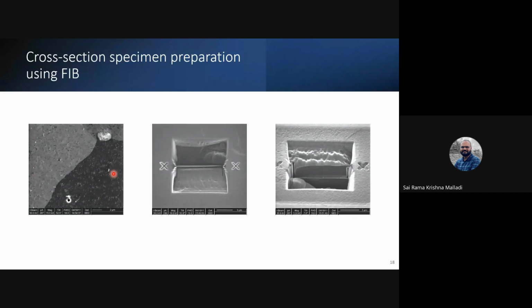So what I can do is, the way you do lithography in clean room processing techniques, I can put in some kind of fiducial markers, or I can make some X kind of shapes here. And these markers would be used as a guideline for my specimen to direct my ion beam to form a trench here. Essentially, what I'm doing is I shoot a beam of focused gallium ions and I raster them in this particular region here, and I mill and remove the material in this area,